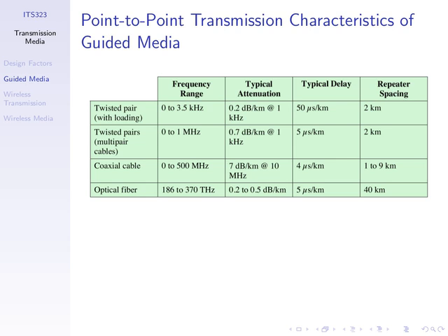Attenuation is how much we lose. The signal attenuates, gets weaker. So this is saying, say, 7 decibels per kilometre. So the loss over 1 kilometre is 7 decibels. The gain is minus 7 decibels.